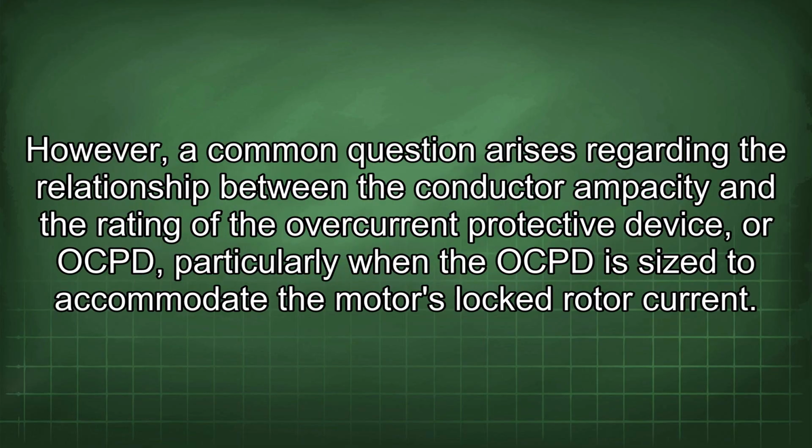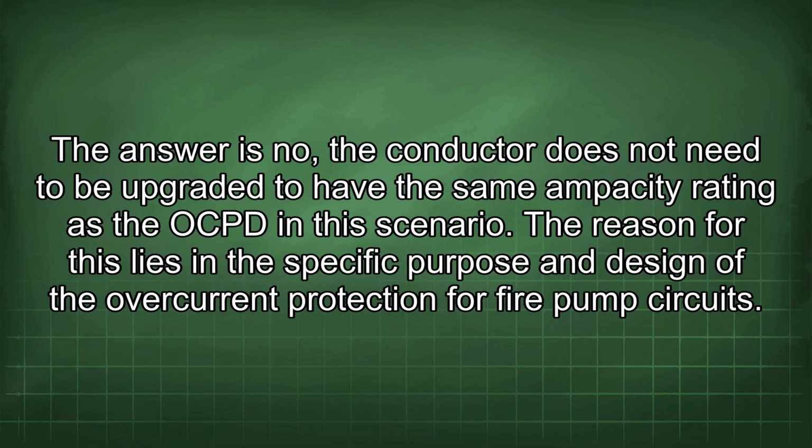However, a common question arises regarding the relationship between the conductor ampacity and the rating of the overcurrent protective device, or OCPD, particularly when the OCPD is sized to accommodate the motor's locked rotor current. The answer is no. The conductor does not need to be upgraded to have the same ampacity rating as the OCPD in this scenario. The reason for this lies in the specific purpose and design of the overcurrent protection for fire pump circuits.